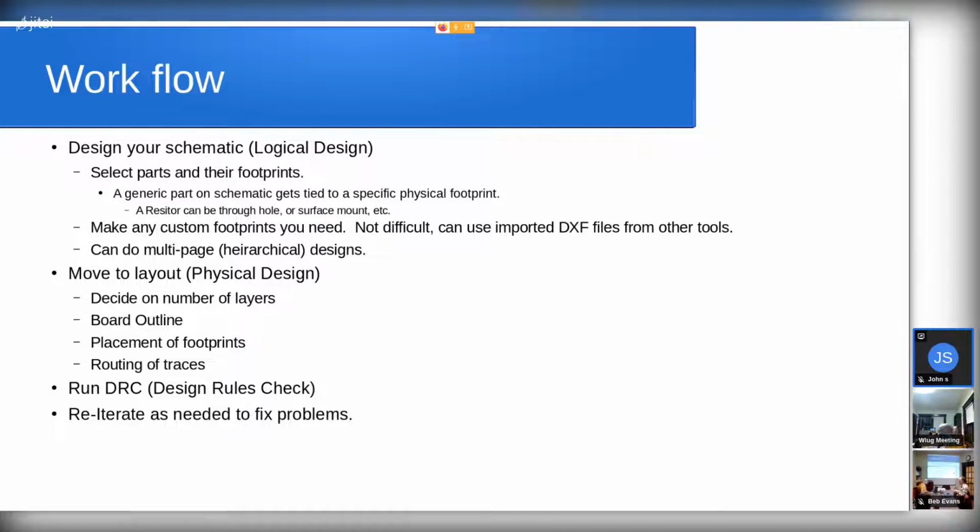And KiCAD does have design rules that you can actually put into the design that say, like, the pins on this net, say you're doing Ethernet pin pairs, like there's 4 pairs coming out. You can put in a design constraint that says these pins must all be within 1 or 2 or 5% of the same length. Yeah. And I think the drawing tool will actually let you lay them out so they're within that, and the design rules check will find and fix that kind of stuff.